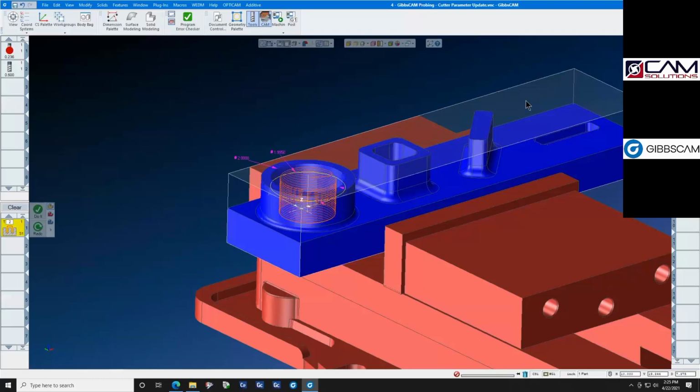If you've had a Renishaw ball bar test run on your machine and you were given a capability certificate of 7/10,000ths of an inch, which means that your machine has the ability to hold 7/10 on a 2-inch diameter bore, we can help you stay at that 7/10 or slightly inside of it, maybe like 6/10.